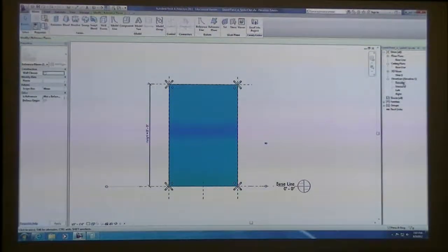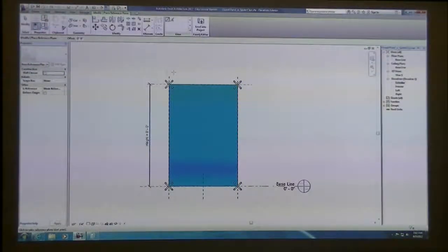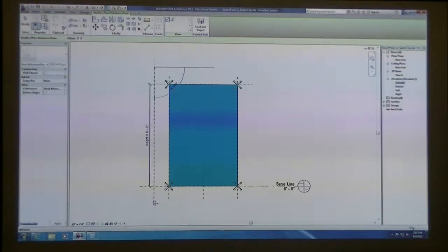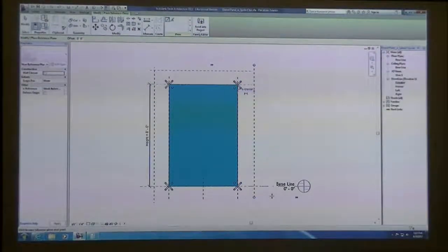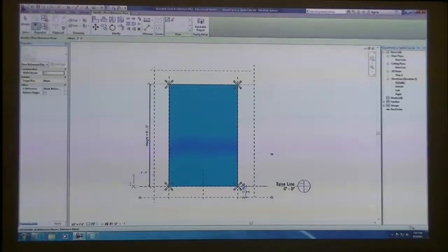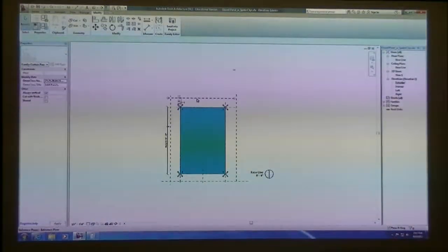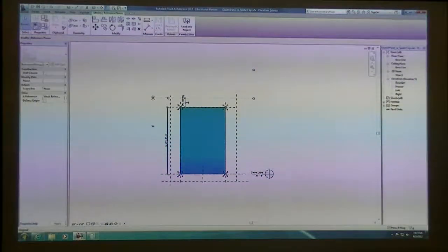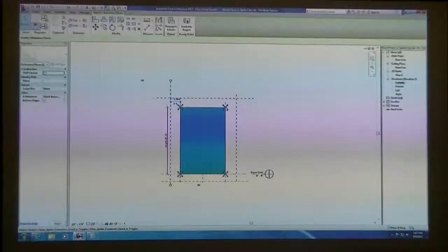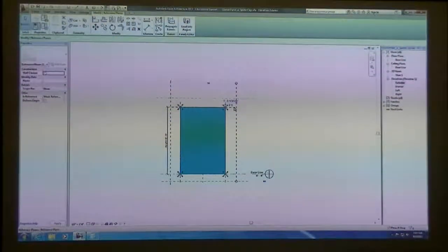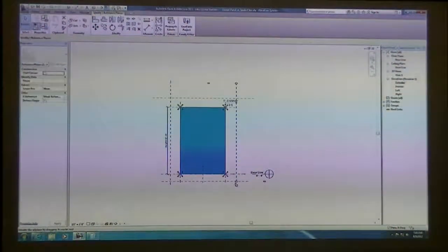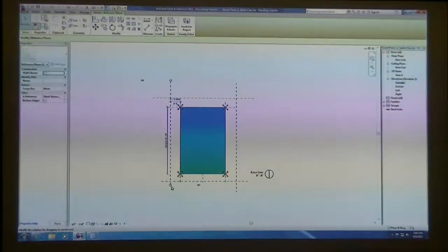So in this elevation view, I'm in an exterior, you could be an interior, it really doesn't matter. I'm going to click on Home, Reference Plane. Now I'm just going to go way off to the sides on the top. Make sure you draw in a horizontal manner and vertical manner. Just kind of far off into space, get your additional reference planes to float, and then I also might just drag my endpoints just a little bit beyond one another.